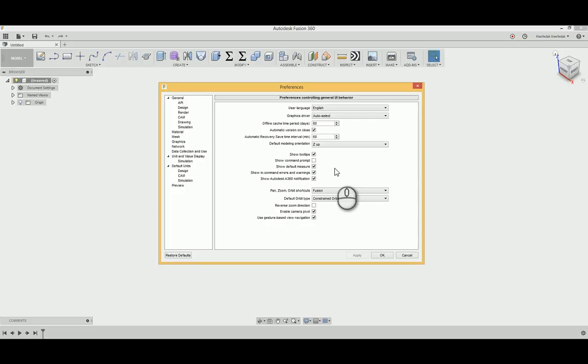And the beds on a printer or on the multicam, that bed is the XY axis. What goes up and down, if it's the nozzle or the extruder on the 3D printer or the spindle, that's the Z axis, up and down. One of the problems that I found is people start modeling things in here and that axis is off and then they're stuck. So we always want the Z up. So put that to Z up.